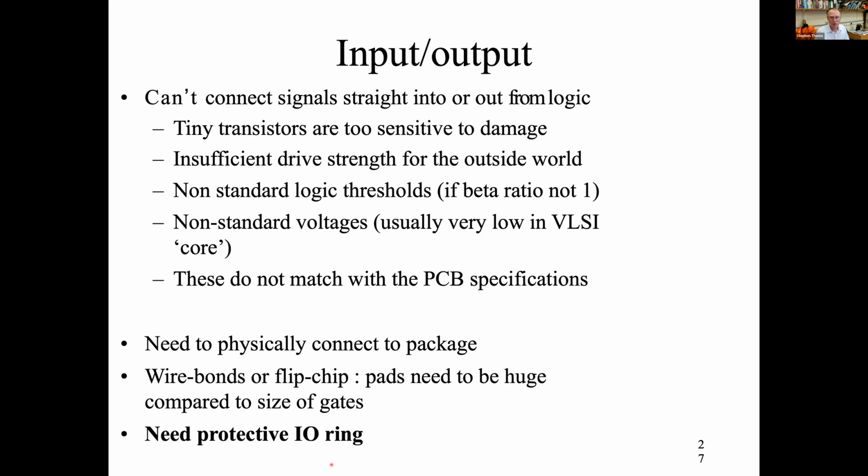The other thing that needs to happen is we need to physically connect to the package, which is done by a wire bond, or sometimes by flip chip bonding. But both of these need big pads, which are of the order of 100 microns or 50 microns. These are huge compared to the size of our gates. And we need some sort of protective I/O ring because of static or whatever. You don't want your chip to be easily destroyed simply by handling or whatever.